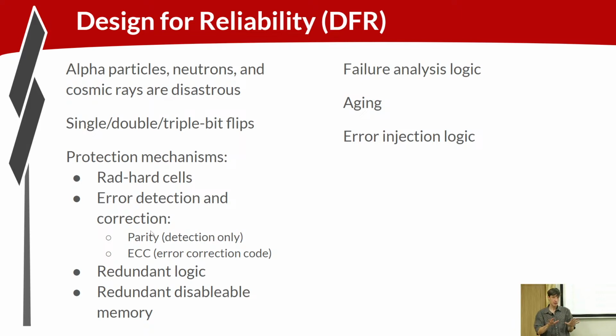You apply these schemes to memory when you write some amount of data, maybe 256 bits. You compute the ECC code for that data before you write it, and you write the data along with the ECC code. When you read the data out, you recompute the ECC and check it. If it doesn't match up, you go into some correction flow, figure out the right data, make the correction, write the correction back to memory, and continue execution.